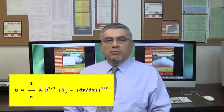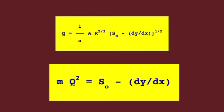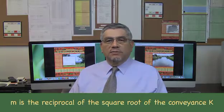The difference between kinematic and diffusion waves is in the flow depth gradient. From a physical standpoint, the flow depth gradient accounts for the natural diffusion process present in unsteady open channel flow. To derive the diffusion wave equation, the previous equation is expressed as follows, in which m is the reciprocal of the square root of the conveyance k, defined as follows.